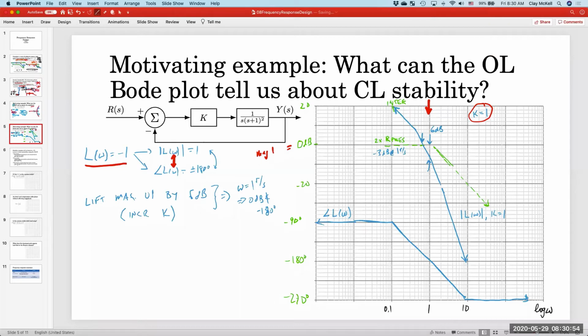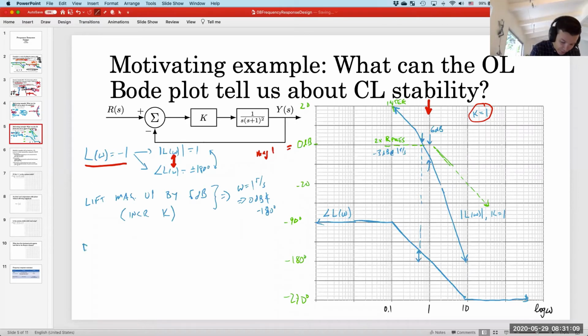If you shift it down. Exactly. If I were to take this frequency and drop the phase plot by this distance, so if I drop the phase by, I don't know, what does that look like? That looks like maybe half of 45, so call it 25 degrees. Then I get this same condition where omega would be, I don't know, 0.2345.